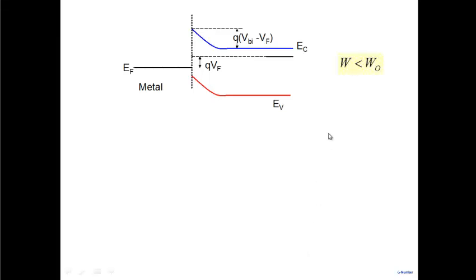All right. So as I said, if you apply a forward bias, we have seen the energy band diagram. The net voltage becomes smaller here. This implies the depletion width becomes smaller than the equilibrium depletion width here.